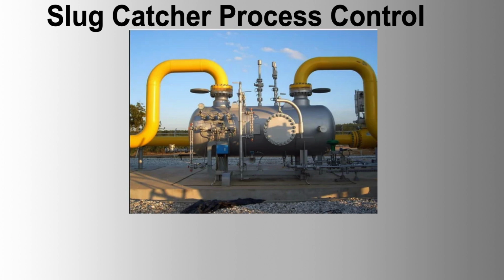3. Emergency shutdown, ESD. Trigger: manual activation or detection of critical fault conditions, e.g. fire, gas leak. Action: shut down all inlet and outlet flows, activate emergency pressure relief systems, and isolate the slug catcher. Maintenance and best practices.